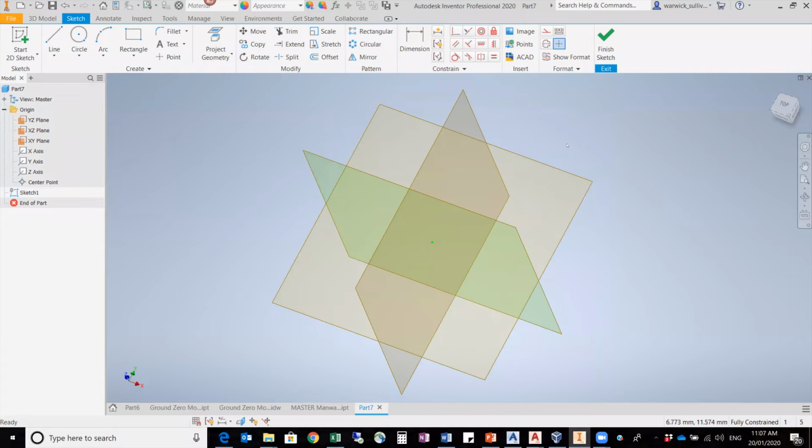All right. Now, what I'm going to do is actually add two crosshairs across here, because at the end of the day, your sketch actually has to be constrained to something. So you can utilize the center point, which is fantastic as well. I do that often, but today we'll use some crosshairs. So turn on construction. We're going to project the geometry on this one and this one here. So that gives us some crosshairs so we can put dimensions and sketch on it on this plane. Right click, OK.